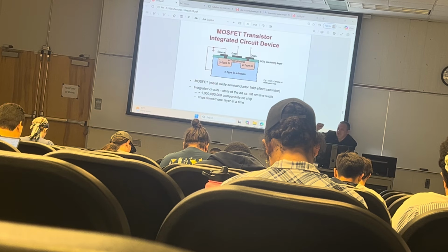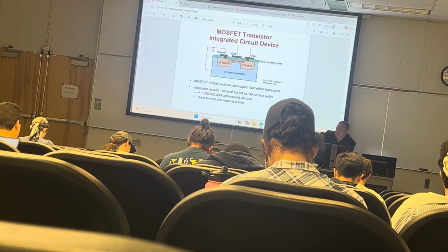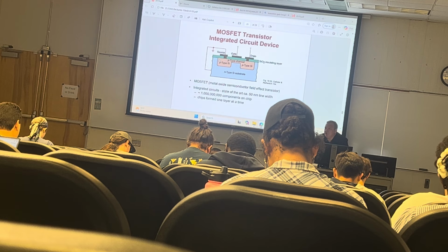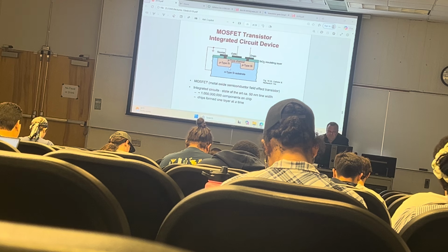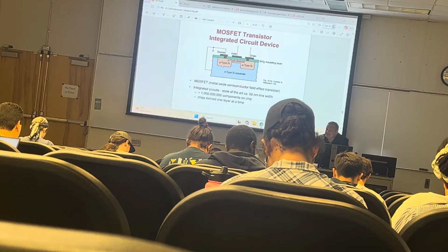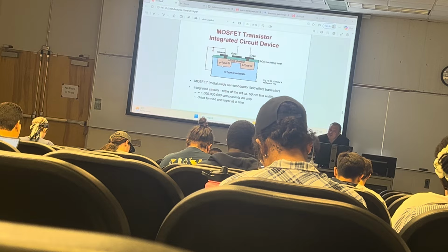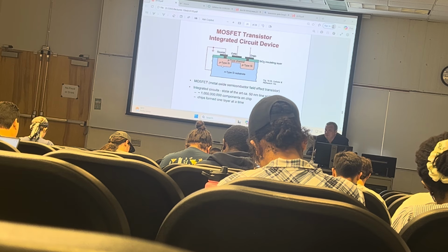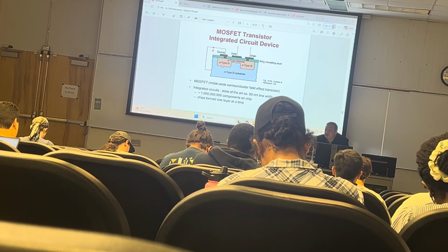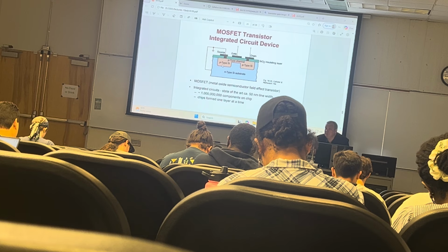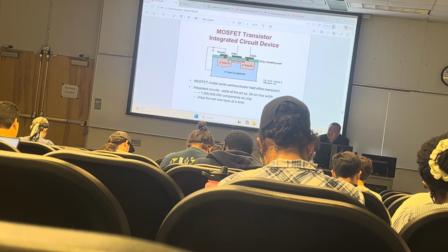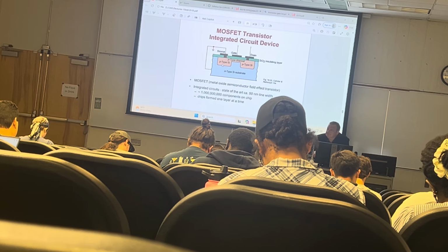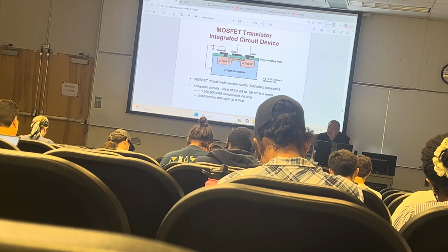So you have a boron layer on the surface of silicon. And then it goes through a diffusion process. You put it in a furnace, and boron starts to diffuse to form the P-type areas in the N-type semiconductor. And guess what? The process engineer needs to know and needs to design the process. And what are the two parameters of that process? For diffusion that we studied.